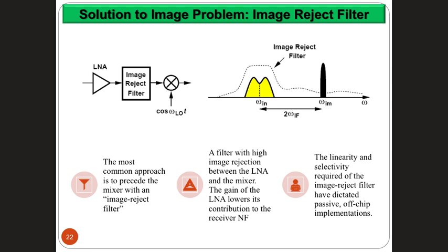And if you lower your intermediate frequency a little bit, this means that your channel selection design can be simpler, but then this means that your image is not that far from you. So you have to take that into account in terms of designing your image reject filter. So it's a trade-off between those two, the image reject and the channel selection filter.